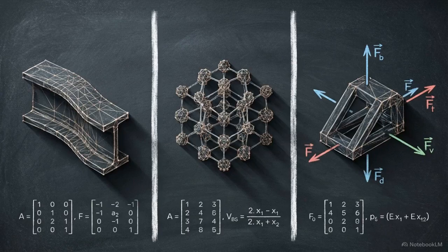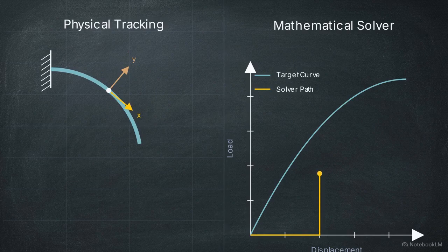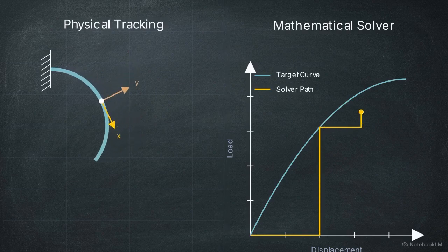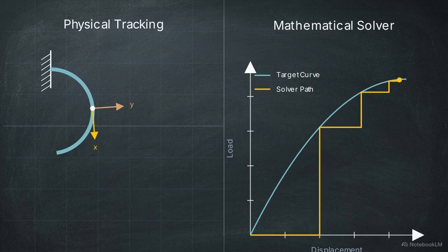This combined architecture, mixed elements and adaptive meshing, is what allows us to solve the three pillars of physical nonlinearity: geometry, material, and boundary conditions. For large geometric deformations, total Lagrangian and co-rotational formulations allow the local coordinate frame to rotate alongside the bending material. To solve these large-scale updates, the Newton-Raphson iterative scheme takes a stepped mathematical path, repeatedly refining until converging on the true nonlinear response.